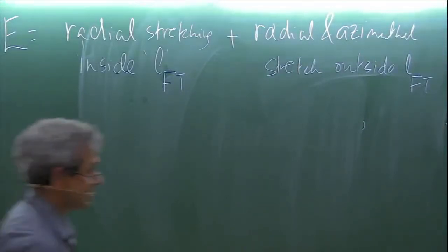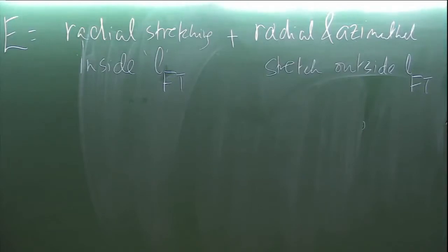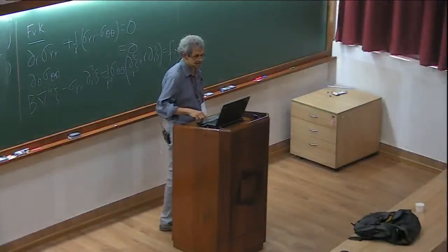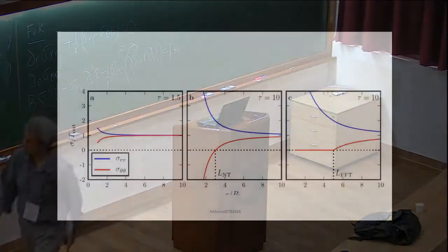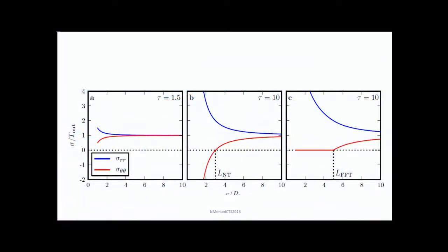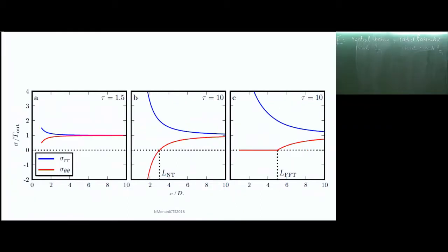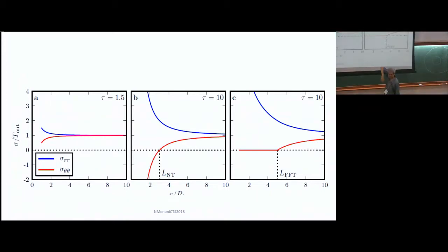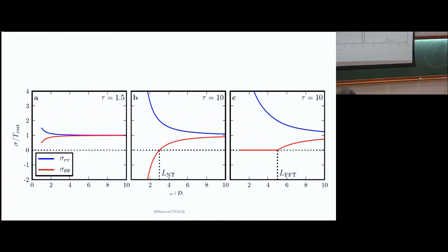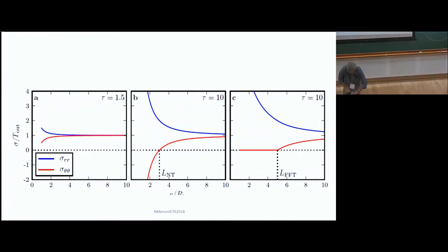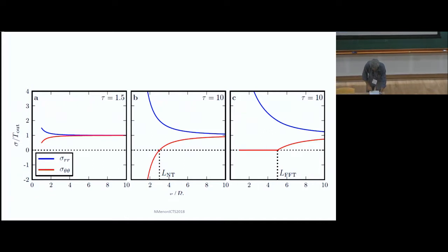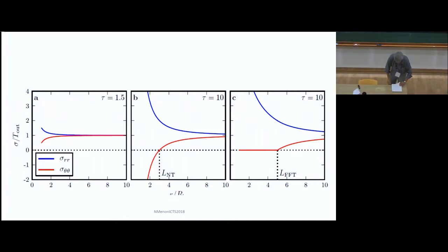So what's happened here is, you get the idea. This is the problem you solved in the first instance. You said, I'm going to take the stable state and I'm going to find where it's compressive. Okay? In the second instance, you solve this problem. You say by hand that the stress is 0 inside where the wrinkles are and solve the rest of the problem. Okay? And this gives correct answers. Now, many comments I have to make here, which are probably more useful than any algebra I've shown you.